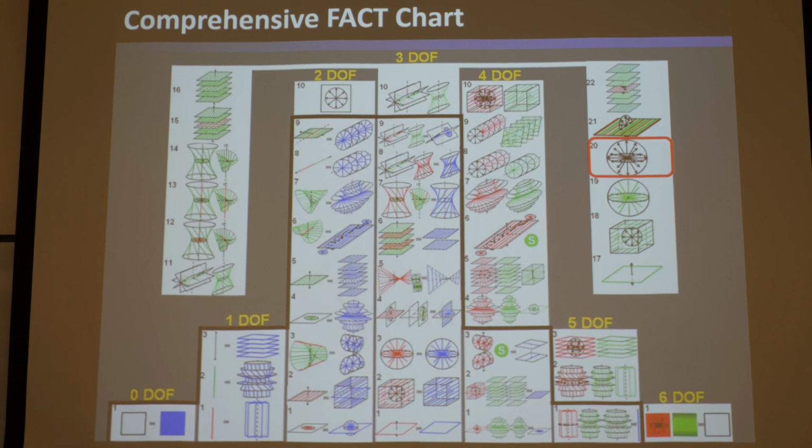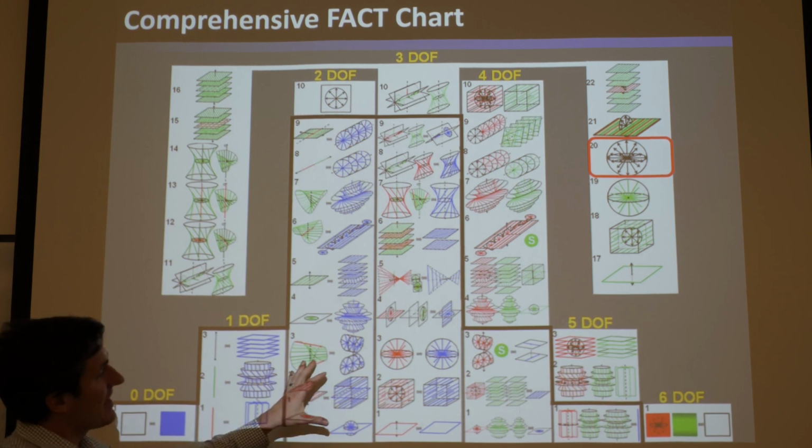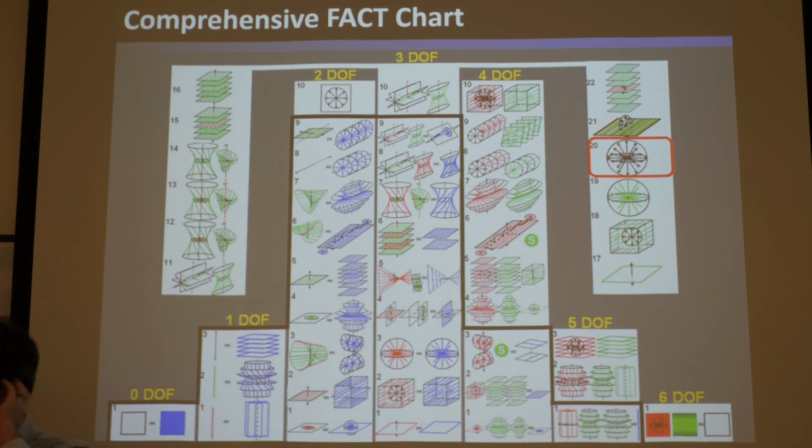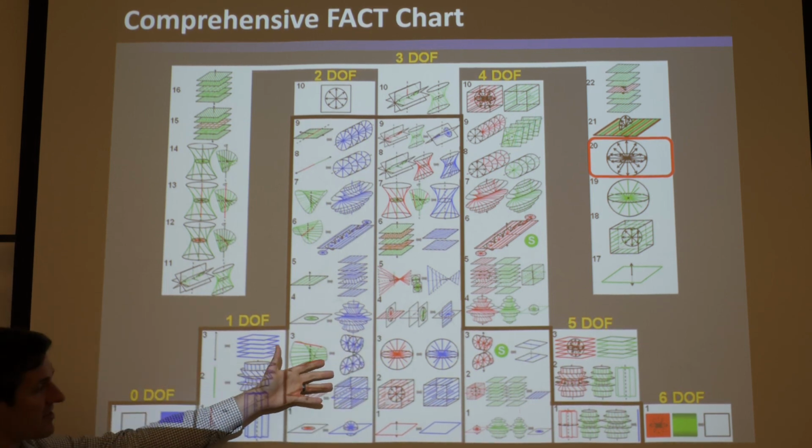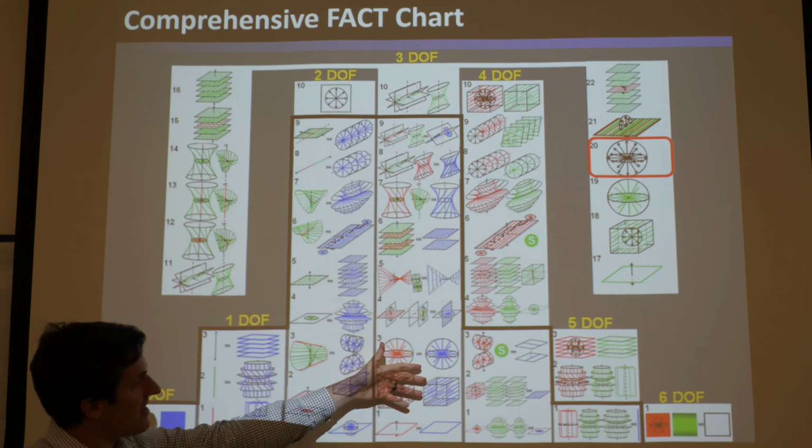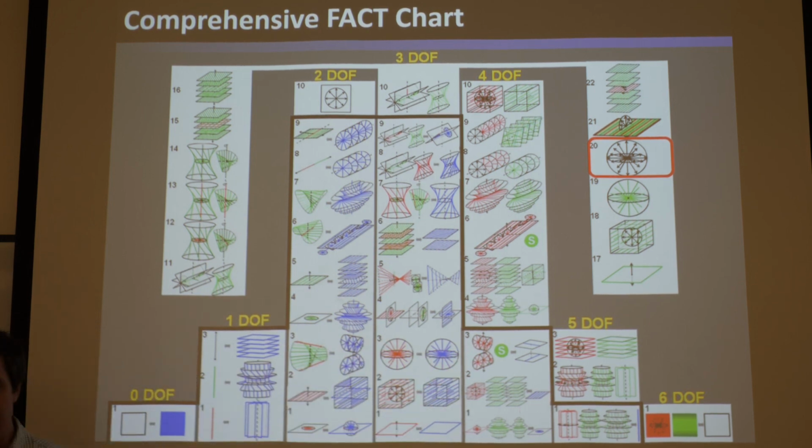That's a very valuable freedom space, right? And you notice it doesn't have a constraint space. There's no way to just synthesize a parallel system from a constraint space that gets this, and so you can't have a parallel system. So it lies outside the parallel pyramid. It's called the parallel pyramid, obviously, because these are the freedom spaces in here that have constraint spaces that can be synthesized with enough wires, blades, flexure elements to directly connect 2 bodies together to achieve that freedom space. Then that's a parallel system, right?